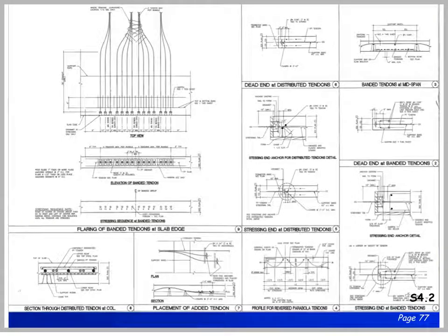On this sheet, we have additional information for the post-tension cables. Post-tension cables are banded wires that add additional compression to the concrete, allowing thinner sections and a lighter structure. After the concrete is poured, it reaches specified maturity and the cables are tensioned. The details here are showing much about how this system works.